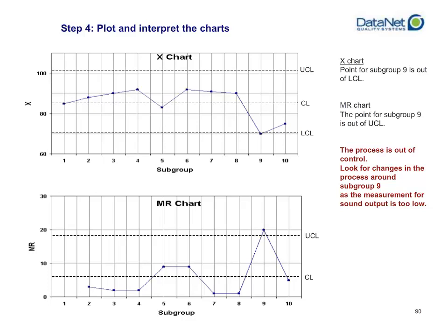When you go ahead and plot your control limits and your X values and your MR values, you're going to see that your process, when you start to analyze this, between subgroups 1 to 8 looks pretty good. Something happened at subgroup number 9 where you were out of control for sure in your MR, in your moving range. The volatility of your process absolutely skyrocketed. And it shows up also in your X chart where you're starting to get low values and extremely low values. You would definitely want to investigate what happened to figure out why that was happening.